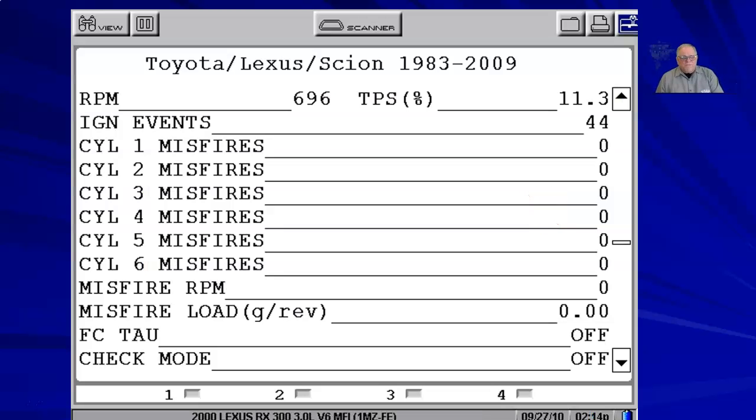If you're working on misfires, this data list that's in here is your misfire counter. Hopefully the manufacturer put this in here. They are required to put the misfire data in there. However, they're only required to put it into mode 6. And mode 6 is a pain to use. Hopefully the manufacturer gives you a data list like this.